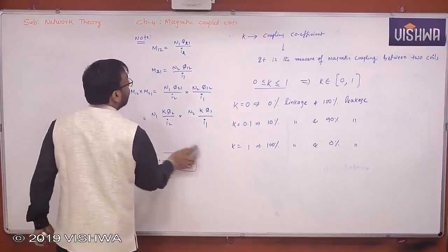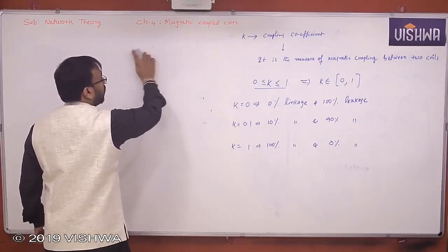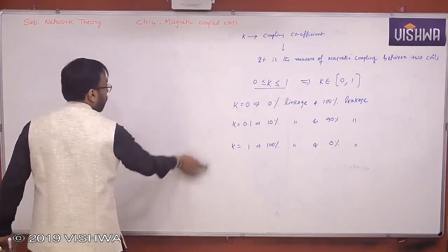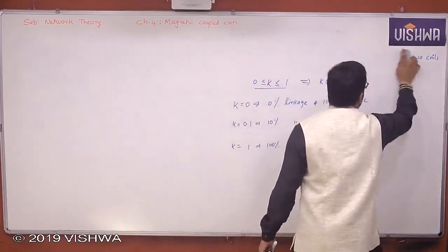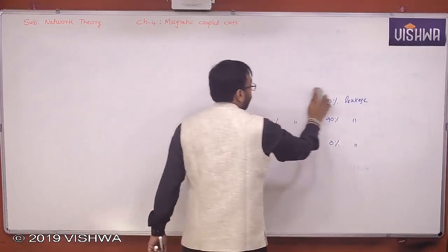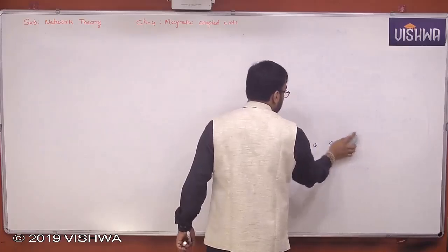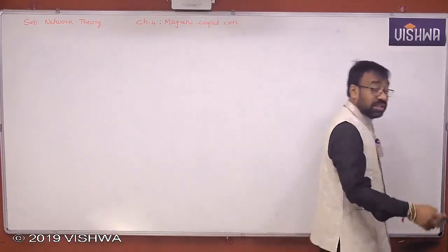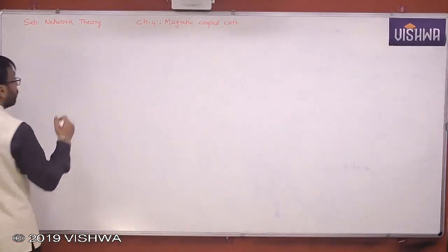Before we started this magnetic coupled circuits chapter, whatever problems we dealt with, in case of inductors and capacitors excited by the AC sinusoidal source, all those come under electrically coupled but magnetically isolated. There was no concept like mutually induced EMF, only self-induced EMF. There we know how to indicate the sign of the self-induced EMF, so identifying it is not a problem. What is the problem here? The sign, the polarity of the mutually induced EMF.